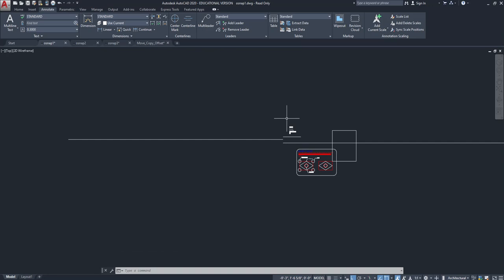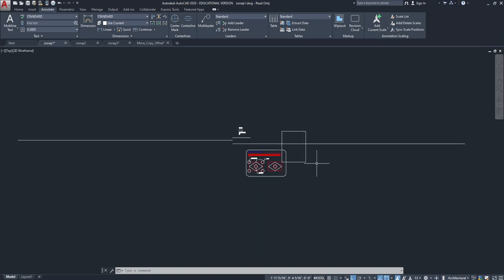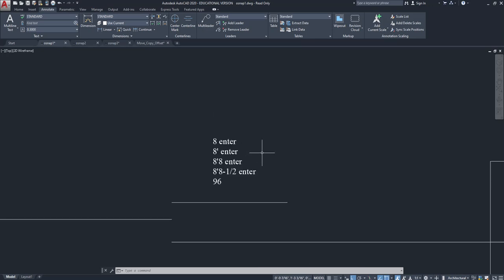So here's a little bit of a tricky thing, all right? I'm typing in imperial units right now, feet and inches. The reason AutoCAD is recognizing those inputs is because I have my units set to architectural units. I've defined architectural units in AutoCAD, okay? Which means when I hit L, enter, click, move in the direction I want to go, type 6 foot, enter,